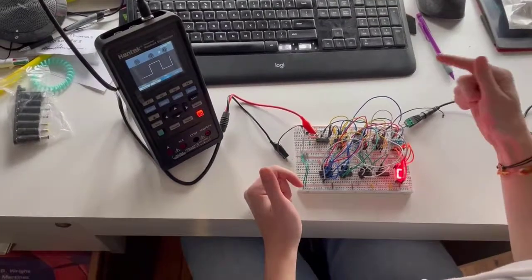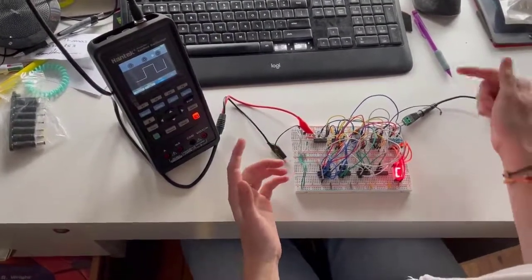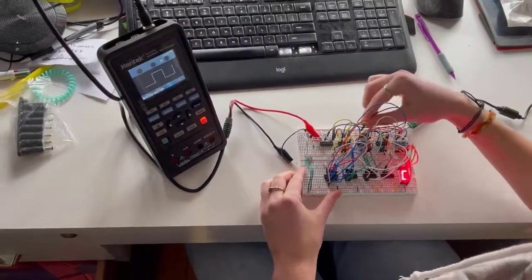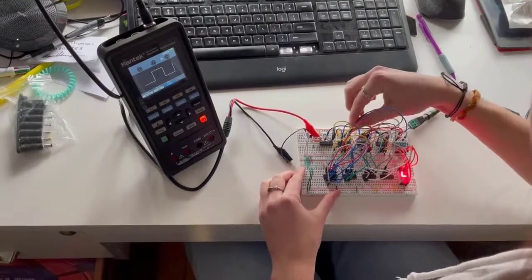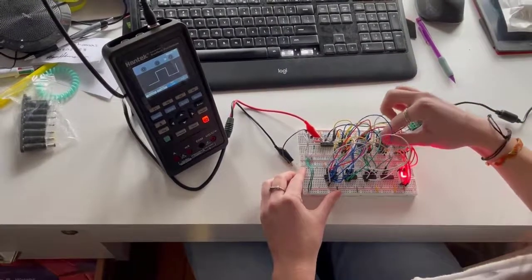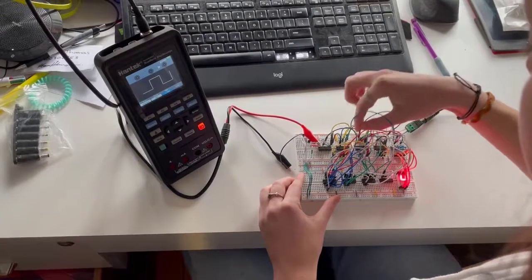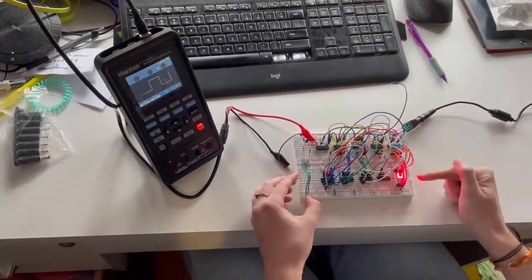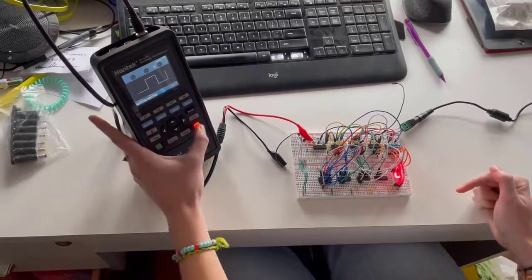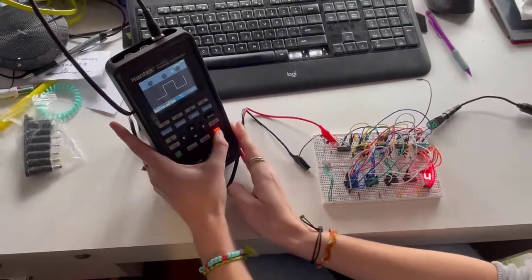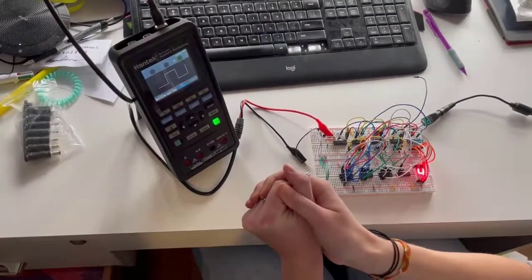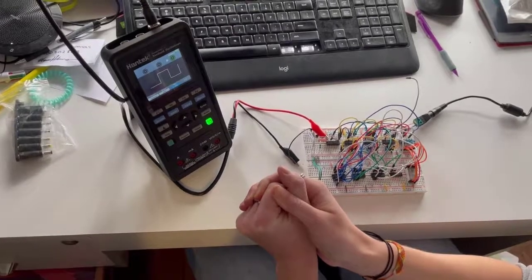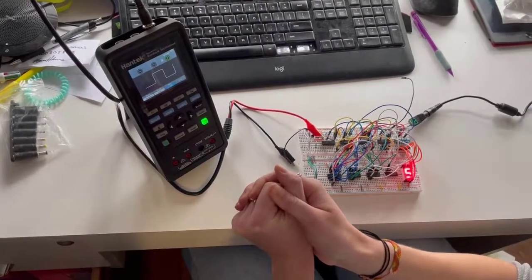I have my presets for the ones that I don't need in my starting state hardwired, and I have the ones that I do need in my starting state using pull-down resistors. So I can tap these to ground to set my starting state. And so now I'm in my starting state of 4. And then when I turn the function generator on, we should see it cycle through my student number. 4, 0, 0, 3, 0, 2, 8, 5, 3.